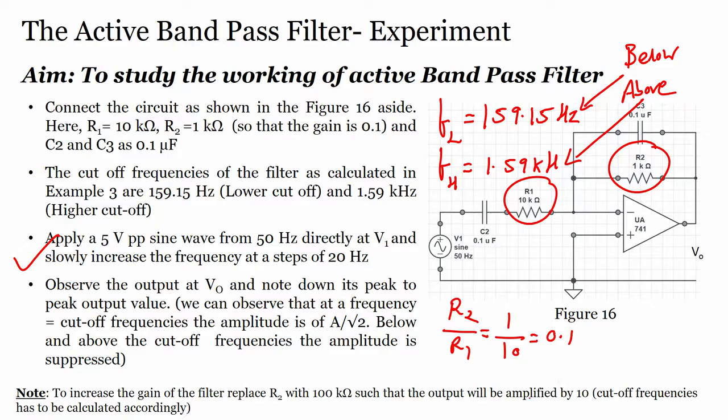That is why whatever signal the band was passing was getting multiplied by this particular factor. That means 5 volts times 0.1 will give us 0.5 volts, correct. So, at the output it was generally close to 400 millivolts, or 300-something millivolts, when we were between FL and FH. You would have seen a voltage of around 350 to 400 millivolts.